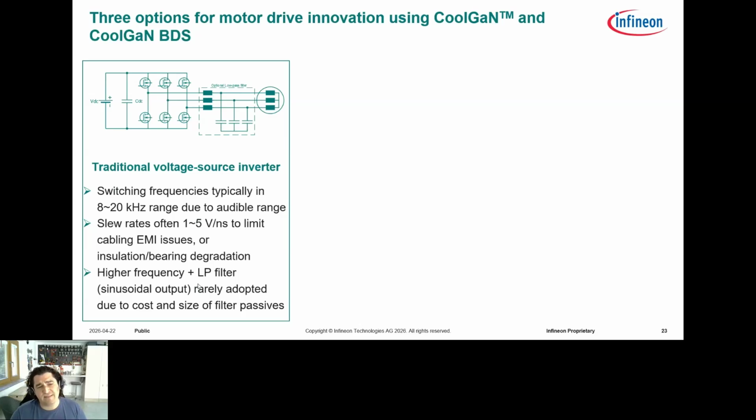You're going to find that there are a number of different issues on the cable from the battery to the motor, one of which could be standing waves from reflection along the cable. One could be radiated EMI. I mean, a long cable, if it's not shielded, is basically an antenna. And then you're just broadcasting your own TV station from that connection from the motor to the battery. So people usually are slowing that down a bit. It probably can go higher than 5 volts per nanosecond, but how much higher depends exactly on the architecture of the system, the length of the cable, a lot of things.